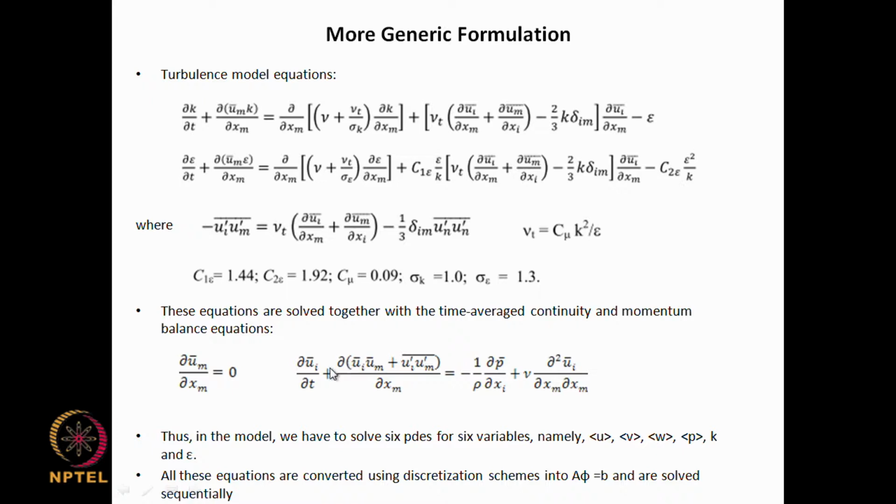a momentum equation which is all in terms of time average quantities, time average velocities and pressures and all that. So now you can solve this using, for example, the SIMPLE method, and so you can get from this the u bar, v bar, w bar, and then those things are also coming here, and you can discretize this using our FTCS and FTBCS type of thing, but you have a source term which is quite active, and it also couples all the equations, but we have laid down the general principles by which we can solve a scalar transport equation.